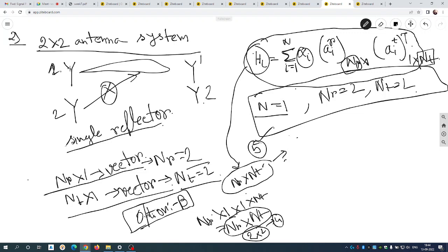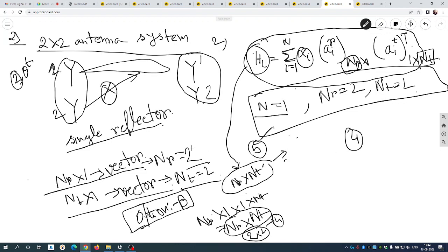So for the second question, there are two transmitting antennas and two receiving antennas. For these two, there will be two angles of departure theta t. There are two parameters, and if I think from the receiver side, there are also two angles of arrival. So 2 and 2 becomes 4, and there is the channel here, and this channel has a gain alpha i according to this equation.